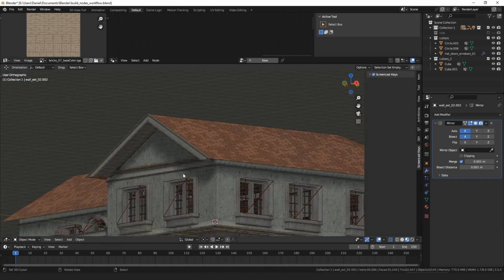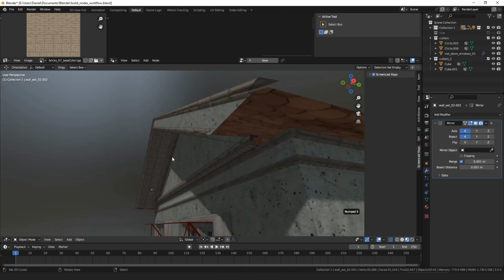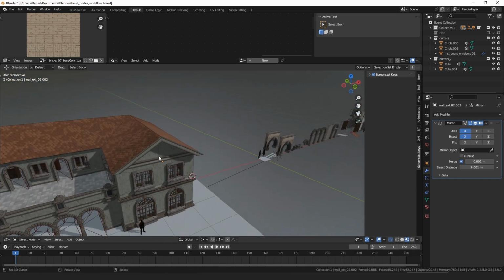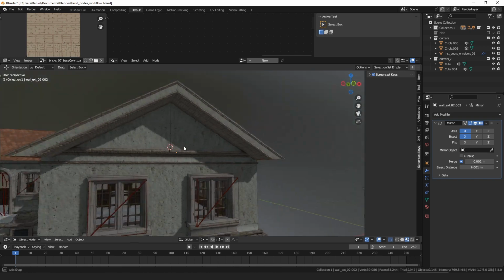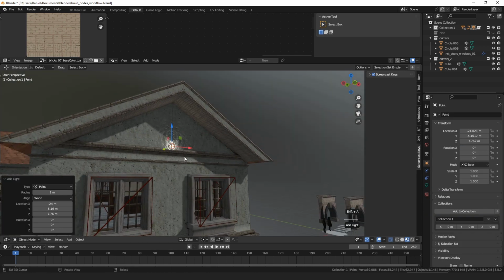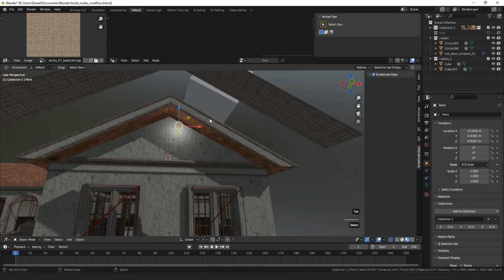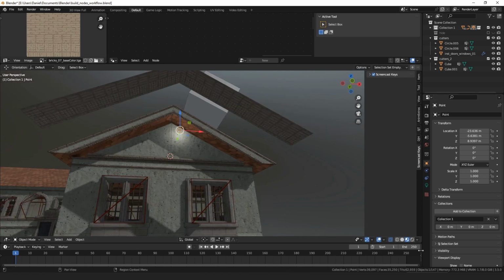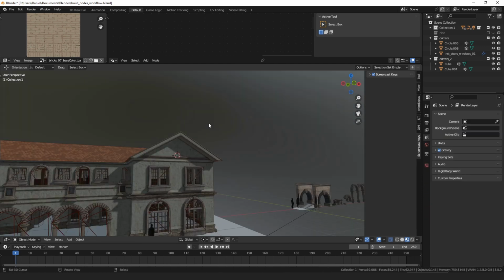Now, even though I don't think there'll ever be an angle where you'll be able to see this face in my game, if this is a building I put in my game, because it's a top-down view, you sometimes do want to put those faces in, because if you have a light, depending on if the back face is allowed to cast shadows or not, you could have bad lighting. I think in Blender it must do that by default. But I know in Unity back faces don't cast shadows by default. So sometimes you want to include faces you'll never see in the final render, because the shadow casting camera will need to render it for the shadow mask.